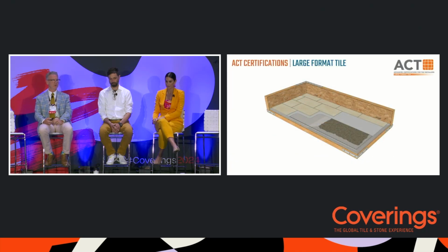So on the test for large format tile, the installers are evaluated on their ability to assess the flatness, to fix the flatness of the substrate, to spread the mortar in the right direction, to get good coverage, that 85% coverage that we talked about, to have minimal lippage. I think Ryan talked about the 33% offset bonding, so no 50% offset bonding, but 33 is okay in this example because of the lippage. So, and that's only a handful. These are some of the critical points for large format tile. They don't grout this. They just fix the substrate and they lay the tile.